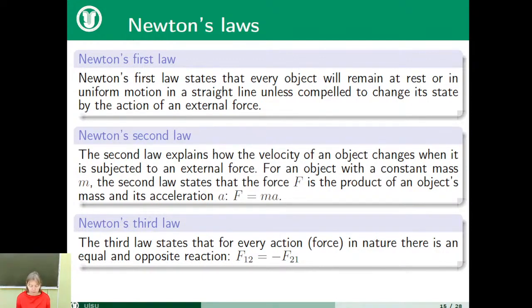Only forces that act on that body are to be included in the vector sum, not forces acting on other bodies that might be involved in the given situation. Every time you work a force problem, your first step is to clearly state the body to which you are applying Newton's law.